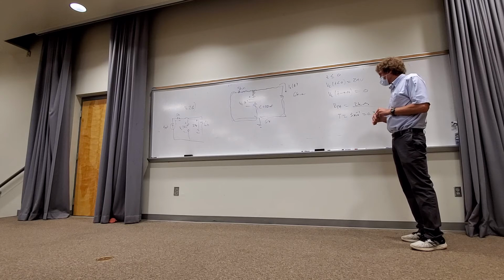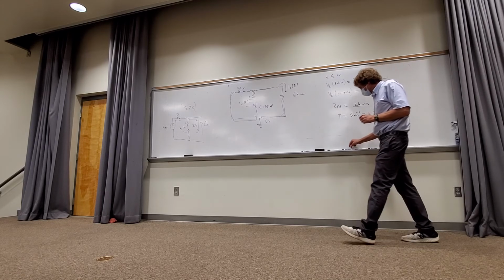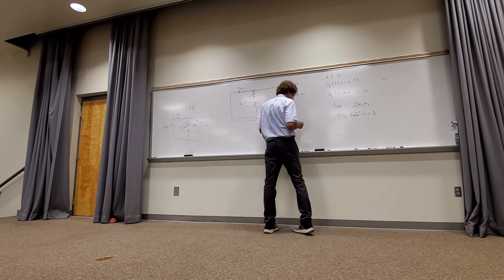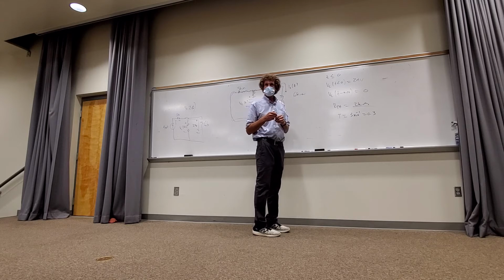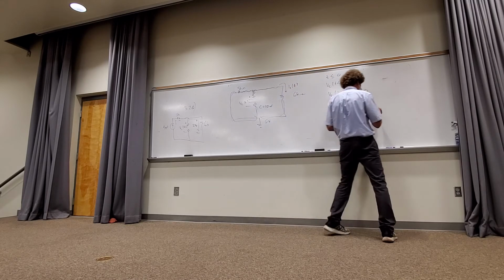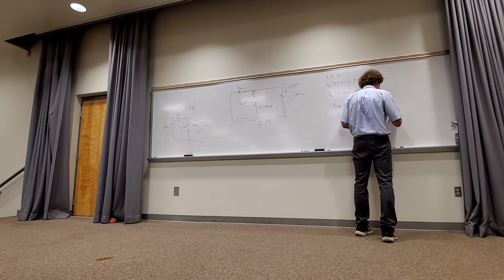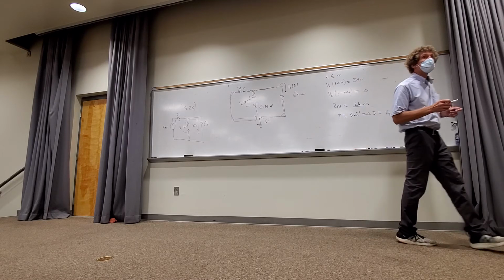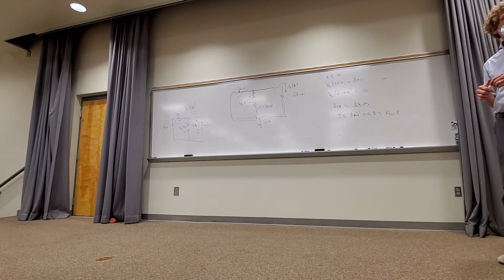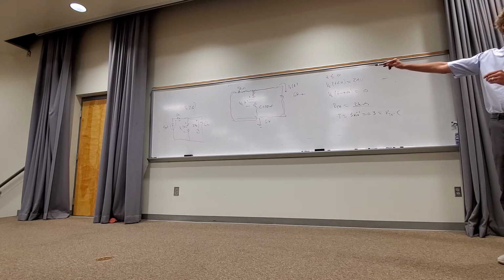You agree with that? All right, so now I've got tau. What's my final step? Can you go through a little bit more on the math solving for tau? It's R Thevenin times C, isn't it? You follow me on that? All right, R Thevenin is 2K. C is 150 microfarads, right?